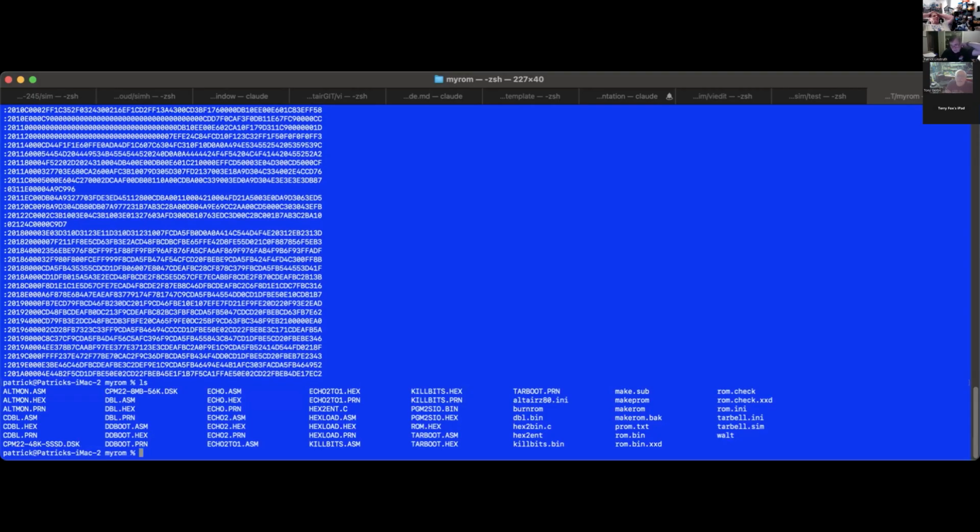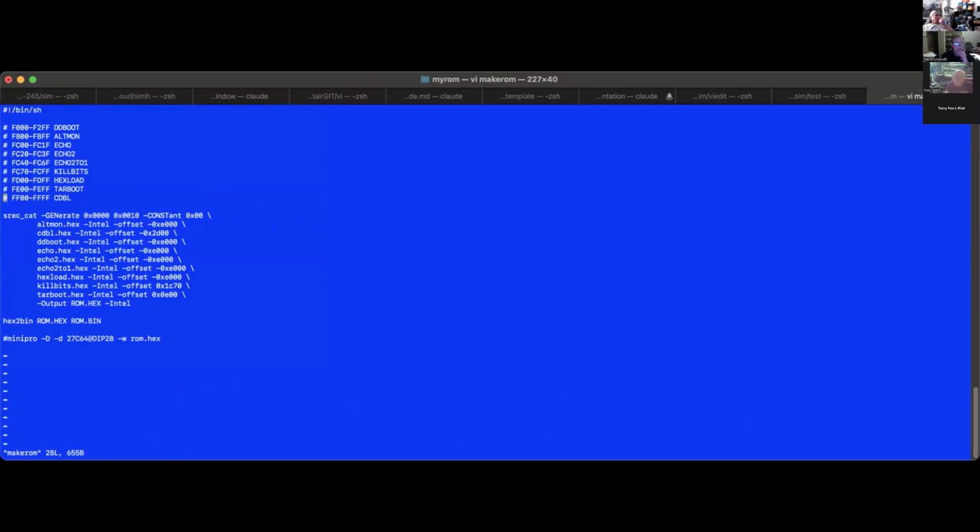For some people it is, because you don't have to consider addressing. If you were to compile a program and it started at 100 hex, and you export that as an Intel hex file, then the very first line will have 100 as the starting address, because that's what you compile the running code to. But you're not putting it in the EEPROM. It'll try to start it at 100 in the EEPROM, but that's not really where you want it. You want to start at the beginning of the EEPROM, stick the EEPROM in a memory board, and then offset that EEPROM to start somewhere else.